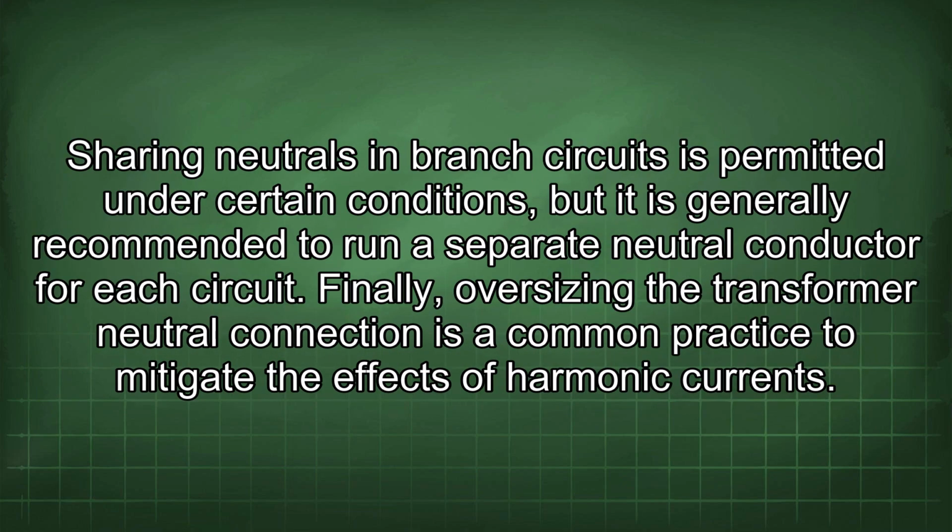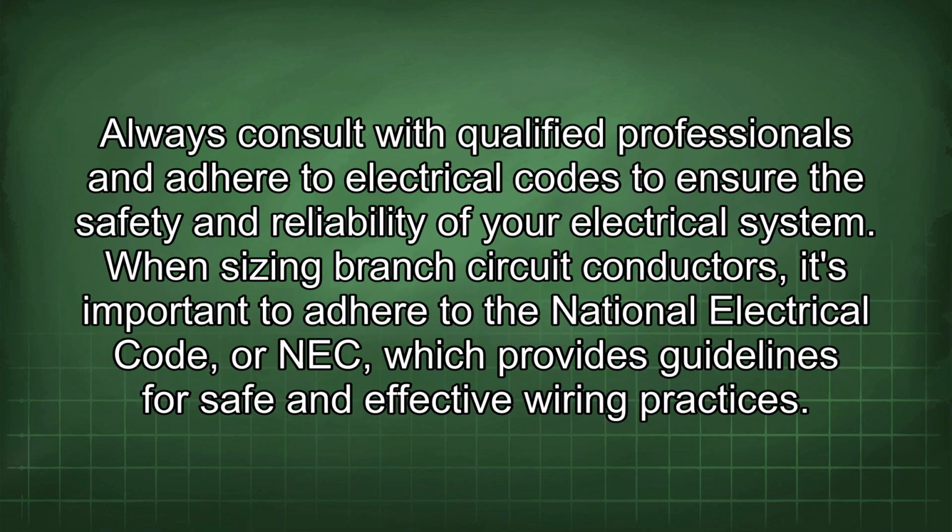Sharing neutrals in branch circuits is permitted under certain conditions, but it is generally recommended to run a separate neutral conductor for each circuit. Finally, oversizing the transformer neutral connection is a common practice to mitigate the effects of harmonic currents. Always consult with qualified professionals and adhere to electrical codes to ensure the safety and reliability of your electrical system.